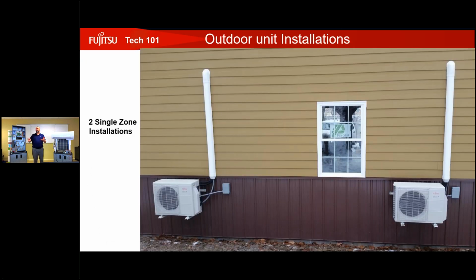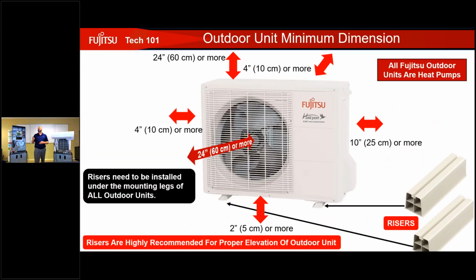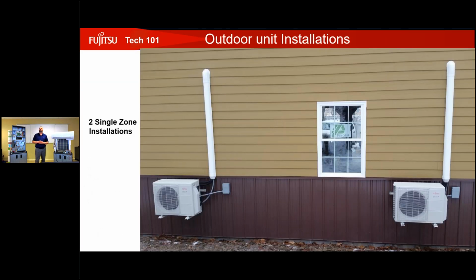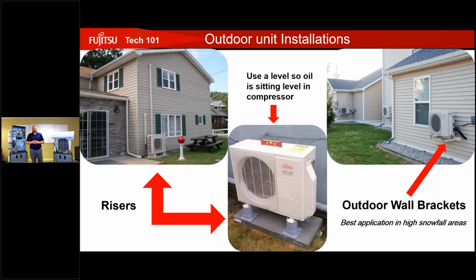All right, we got our units lifted off of the wall there. Very nice. Everything looks good. We might have a little bit of an issue with airflow behind it. We want to try to get at least, what did they say, 6? Oh, they say 4 inches from the back. I like to go a little bit more if I can, just to have extra airflow back there. You can see right here in this photo, this one makes me feel a little bit uncomfortable. That looks really tight there. So something to keep in mind.